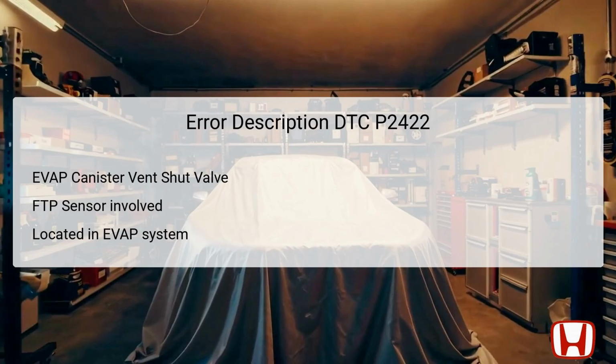The FTP sensor, or fuel tank pressure sensor, is also involved, providing feedback to the PCM about the pressure in the fuel tank. The EVAP canister vent shut valve is typically found near the EVAP canister, which is located under the vehicle, often near the fuel tank.